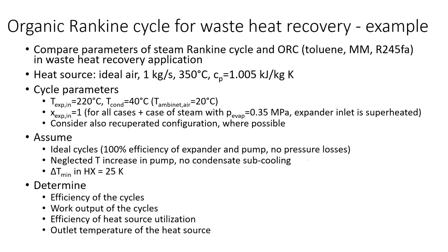Now let's go for the example of the organic Rankine cycle in waste heat recovery that we will calculate. So we will compare parameters of the steam cycle with water and the organic Rankine cycle with 3 different working fluids: toluene, the silicon oil based hexamethyl disiloxane working fluid, and the R245FA refrigerant.